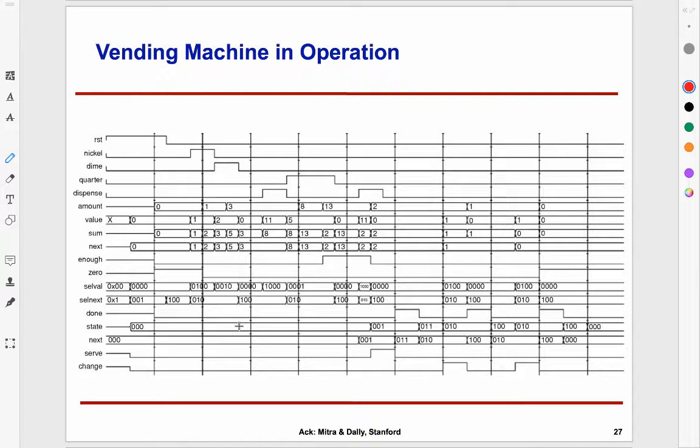So we start out at t equal to 0. There's a reset. So this is the reset part which is happening. And when things are reset, what you see out here is at the first clock tick at which reset is noticed, see the amount is made 0. Okay, so amount is made 0 once we saw the reset, and one thing you can see is this is a Mealy type machine that's happening.